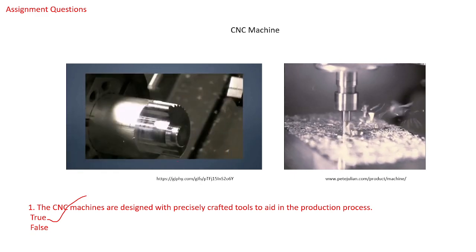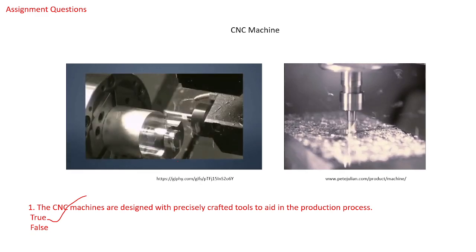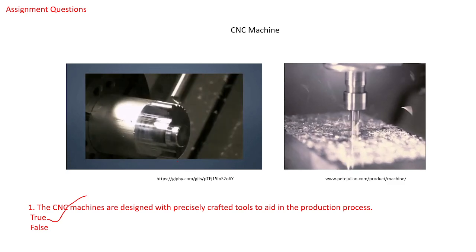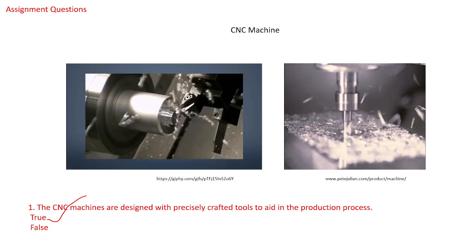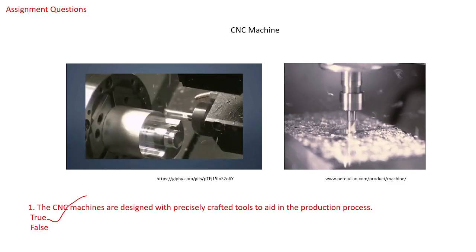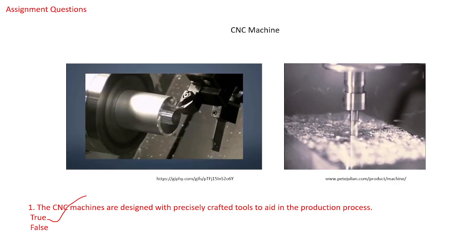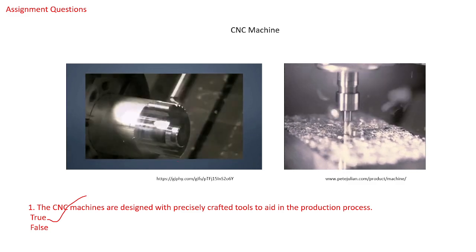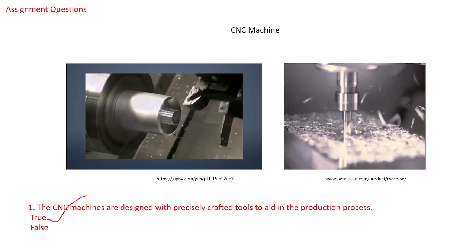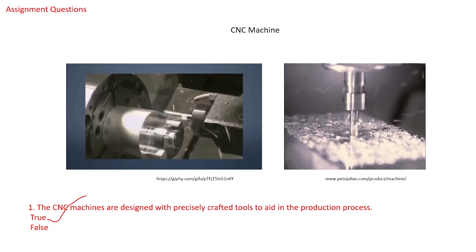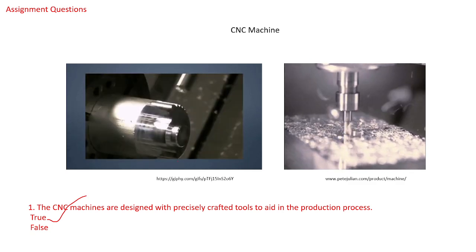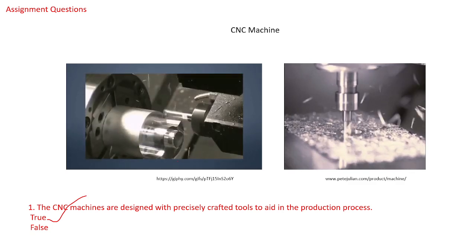Okay, so that machine won't understand the model you design in a CAD file unless it is in a compatible CNC machining file format. That's the reason you need to export your CAD model into a CNC compatible file format with the CAD CAM software. You must have heard about the STL file when you export a design CAD file.